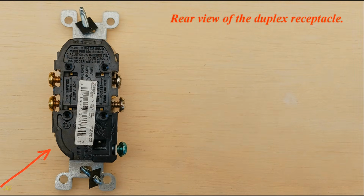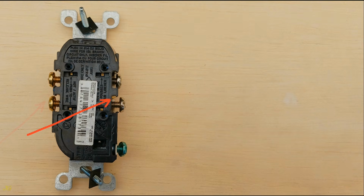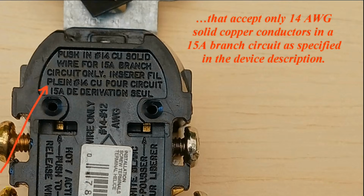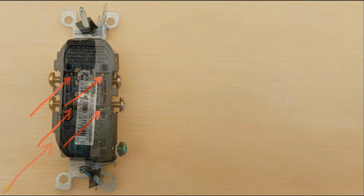Rear view of the duplex receptacle. Ground terminal, green screw. Neutral terminal, silver screws. Hot terminal, gold screws. Push-in neutral and hot terminals that accept only 14-gauge solid copper conductors in a 15 amp branch circuit, as specified in the device description. Push-to-release tabs to remove inserted wire.